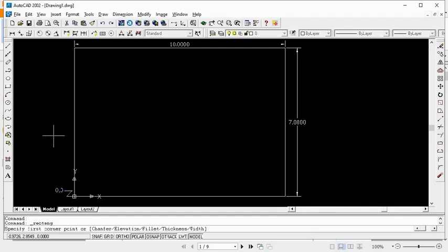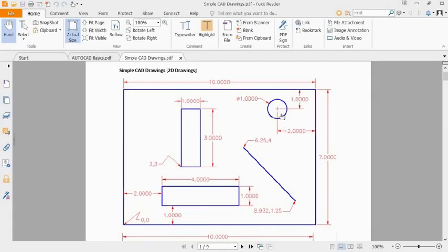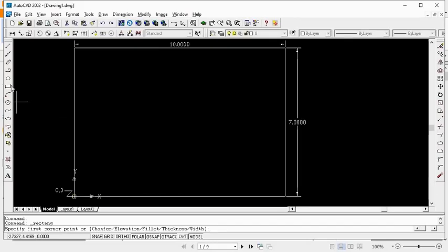The rest of the inner items, the rectangle, the line, and the circle, I want now to draw them. The first rectangle, like the framing rectangle, the other rectangles are also drawn using only two corners, the first corner and the last corner. You specify two corners of a rectangle, and the other two corners automatically follow, based on the first two that you have put. So you only need to specify the coordinate of this corner and the last corner, and then the rest are automatic.